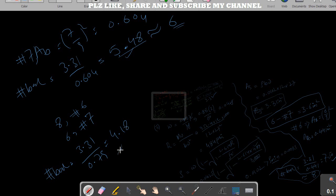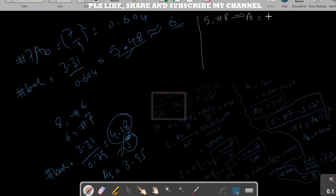Now if I round this to 5, if I am using 5 number 8 bar, it will give me an area of steel 5 times 0.79, which is 3.95 square inches.